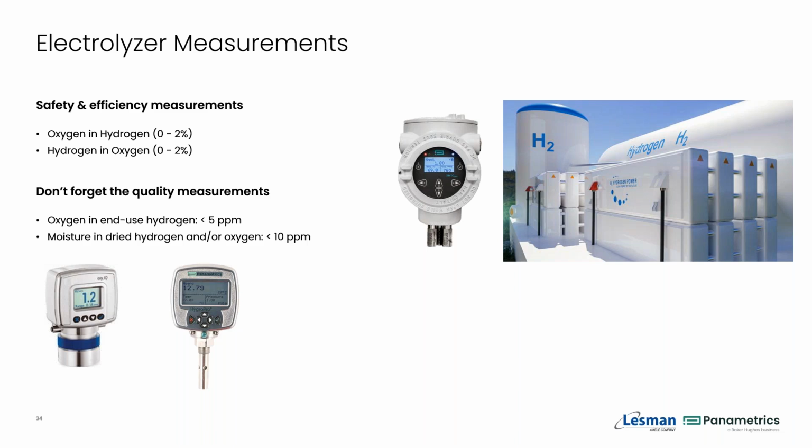And there are really two types of measurements being made here. One is safety, keeping the oxygen level in hydrogen low and the hydrogen level in oxygen low. The way an electrolyzer works is it separates water into oxygen and hydrogen, and it's basically keeping them on one side or the other of a membrane. If you end up with hydrogen migrating into your oxygen, that's an explosive mixture. And if you end up with oxygen migrating into the hydrogen side, you get an explosive mixture, and you don't need that. No one wants to hear boom in the middle of the night. So that's your safety measurement.